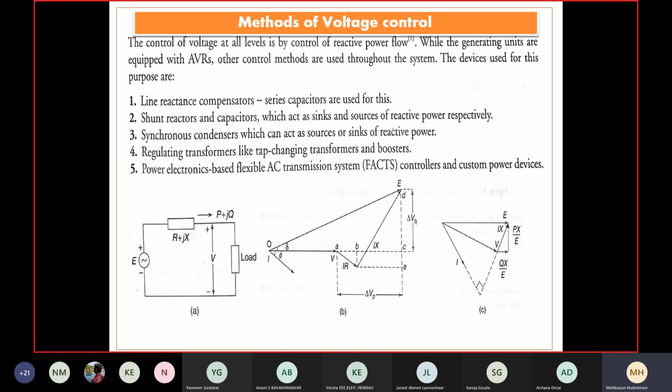At the point of load, suppose there is a delivery of power from bus 1 to bus 2. Bus 2 is highly inductive. The load is highly inductive. So when the load gets connected, the delivery system suffers because of the load nature. So compensation shall be at the load side only. That is how shunt compensation at the load side itself is worked out, which will provide the necessary leading volt ampere at the point of requirement itself. That will compensate the required reactive power, and the transmission system finds effective control of the power flow.